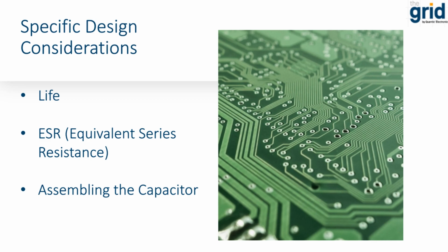Now, surface mount device capacitors, or SMD capacitors, offer a low-cost, large capacitance to footprint ratio, while through-hole capacitors provide reliability under harsh environments due to stronger mechanical bonding. Some designers prefer the use of SMD capacitors, but not all capacitor technologies are available in this format. By considering these specific factors, designers can select the most appropriate capacitor for C-UAS drone defense weapons, ensuring optimal performance and reliability in countering evolving drone threats.